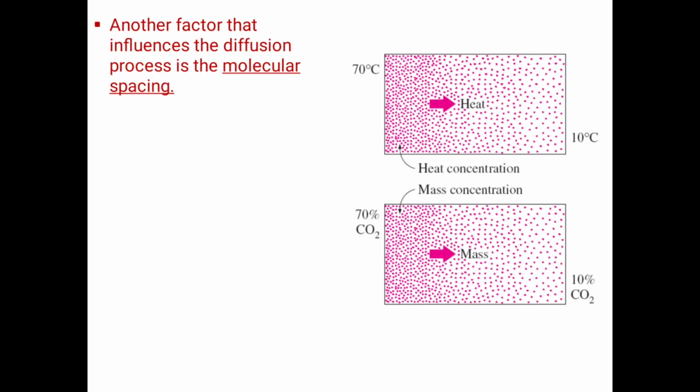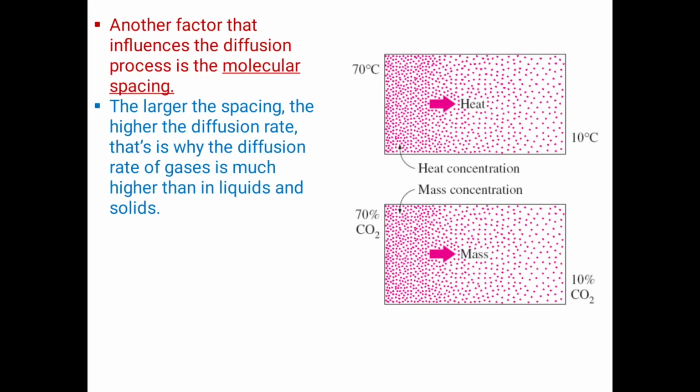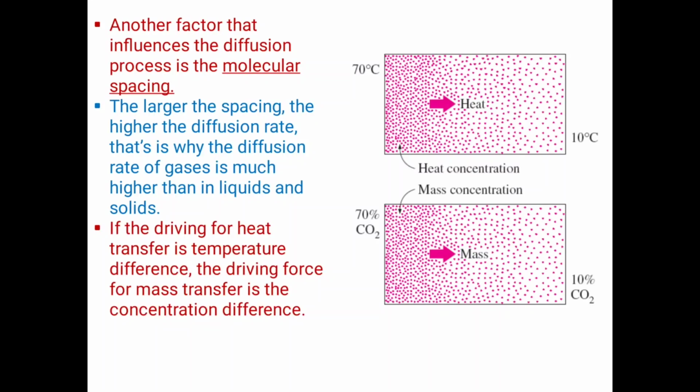Another factor that influences the diffusion process is the molecular spacing. Here, the larger the spacing, the higher the diffusion rate. That is why the diffusion rate of gases is higher than that of liquids and solids. If the driving force for heat transfer is temperature difference, the driving force for mass transfer is concentration difference.